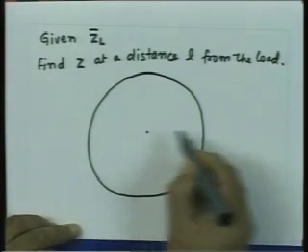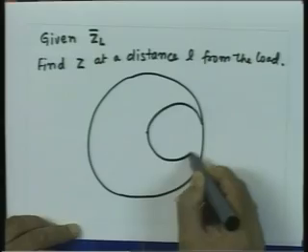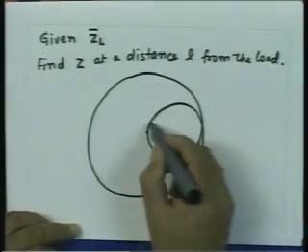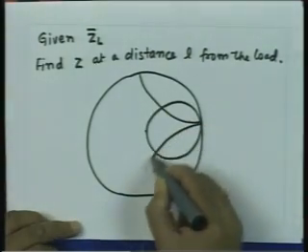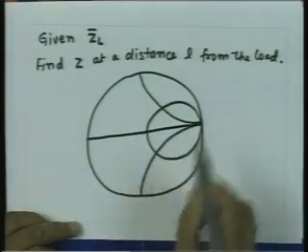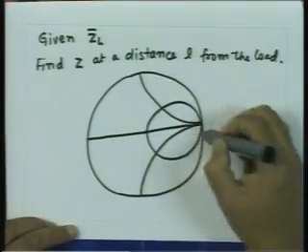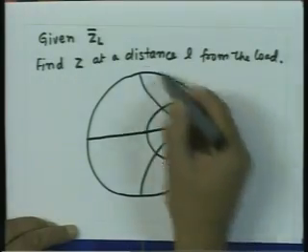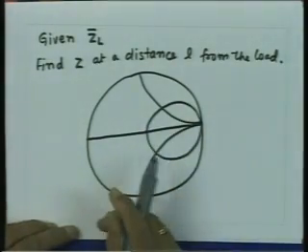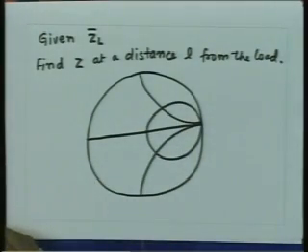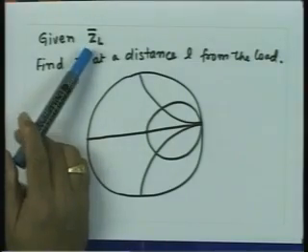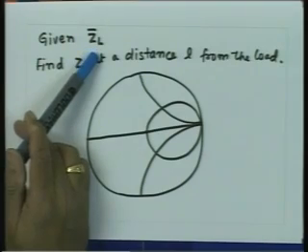Generally, just for clarity to represent the Smith chart, we draw only these 3 circles: the R equal to 1 circle, the R equal to 0 circle, then the reactance circles, which are just 2 circles like that, and this line. So, this corresponds to x equal to plus 1, x equal to minus 1, R equal to 1, and R equal to 0, x equal to 0. Nice. So, normally, just for clarity, we draw only these few circles to represent the Smith chart. Now, the first step is that you have been given the normalized impedance. If the impedance was not normalized, we normalize it first.